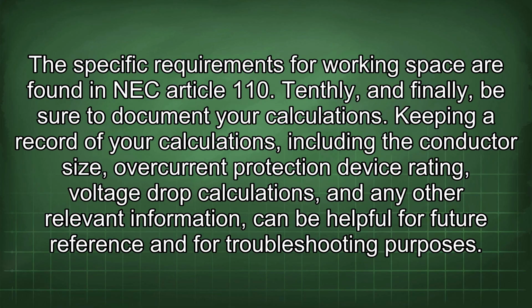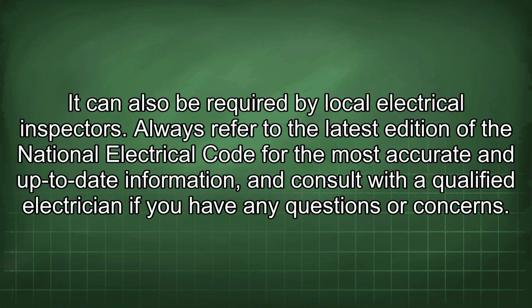Tenthly and finally, be sure to document your calculations. Keeping a record of your calculations, including the conductor size, overcurrent protection device rating, voltage drop calculations, and any other relevant information can be helpful for future reference and for troubleshooting purposes. It can also be required by local electrical inspectors.